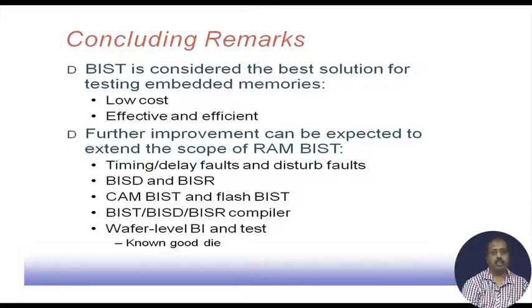So, as far as memory testing algorithms are concerned, it is dependent mostly on the march sequence generation, and we have seen that unlike other test pattern generation algorithms, ATPG, here it is based on simulation. So, you can have your own test generation procedure. You can think about any way of generating these read write commands, and then you can take help of this simulator RAMSES to check whether the faults are getting covered properly or not, and accordingly you can get a confidence about the quality of the test generation algorithm that you are proposing.